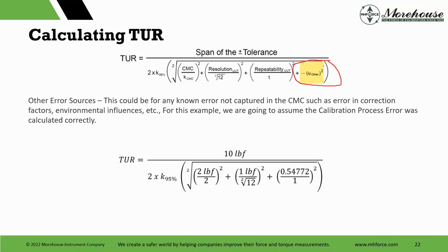we have thermometers galore. We have 5 remote ones that we're doing tracking, SPC tracking and everything else. And then we have really good ones, those are accurate, I believe, to 0.1 degree. And then we have some Hart units, later bought by Fluke, that are good to about 0.01, better than 0.01.